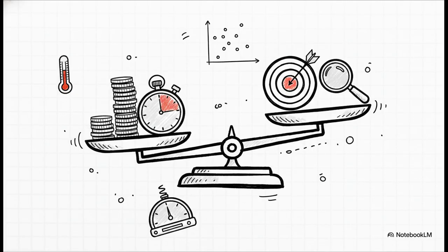As we move from theoretical datums to actual measurement planning, things get messy. Do we always measure in a perfect, climate-controlled 20 degrees Celsius environment? Absolutely not. Do we take an infinite number of points on a part's surface? Impossible. Do we use measuring equipment that has exactly 0 error? Never gonna happen. Every single measurement you take is an estimation. That's just the truth of it.